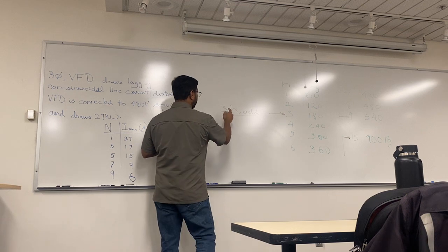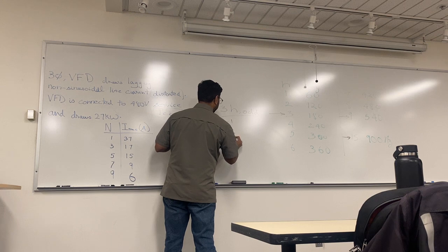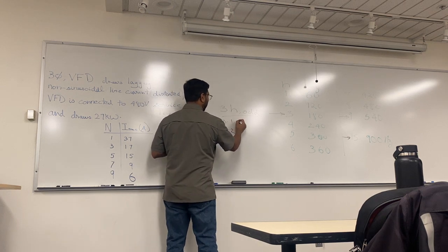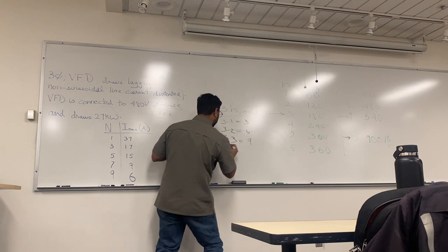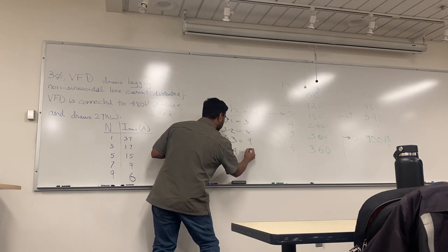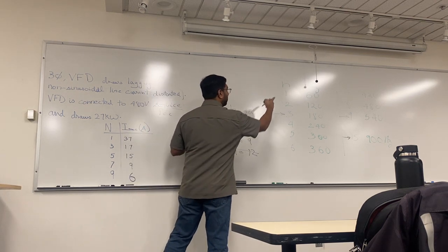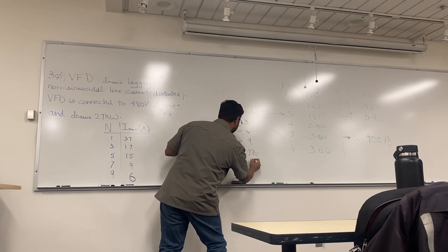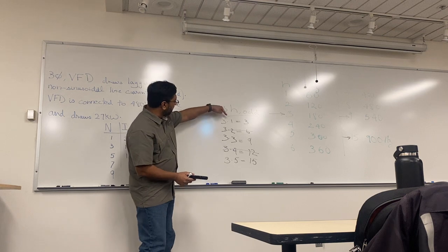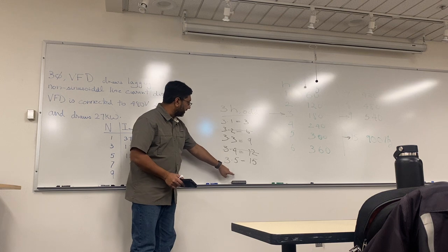The other way to look at it is 3 times 1, 2, 3. Put any number for h. And if you get an odd number, yeah, you need to pick that up. 3 times 2, 6, not required. 3 times 3, 9, required. 3 times 4, 12, not required. This is how you will find it in the text. So 15 is required. So what this is telling you is 3 times h, where h is your harmonics, 1, 2, 3, 4, 5, 6.